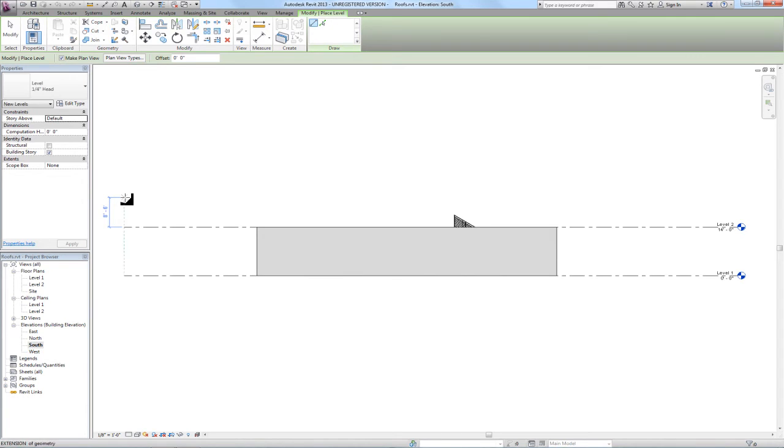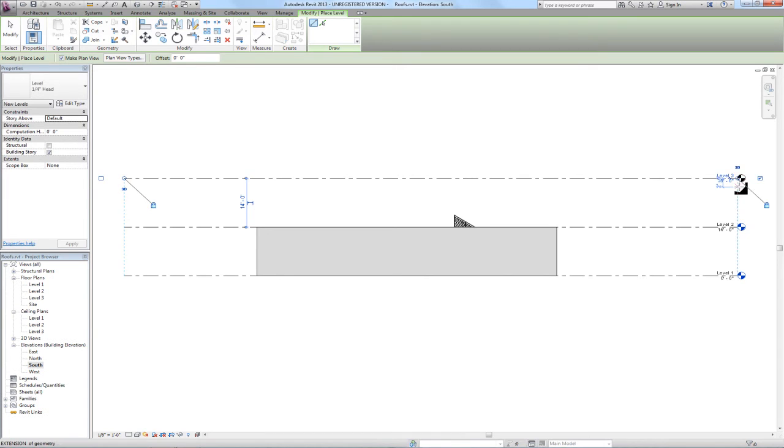and then we can move that so that it aligns with the end of a previously drawn level. We can also try and get it to the particular height we want, but this could be changed easily later. But by getting the ends to line up and seeing this green dashed line, the ends will all move together if any of the level datums are adjusted. Same with this other side. We can wait until we see this green dashed line, go ahead and click to place it, and you'll notice